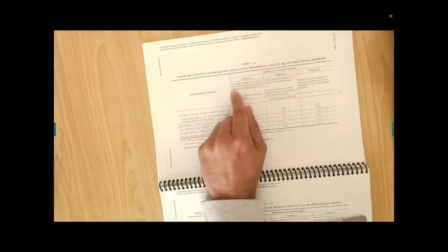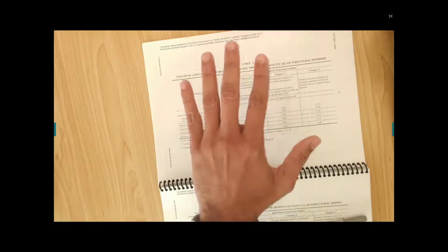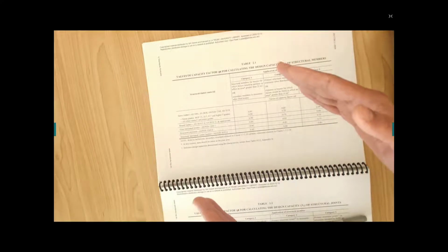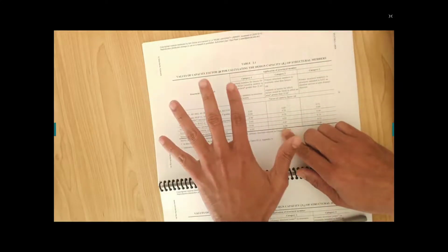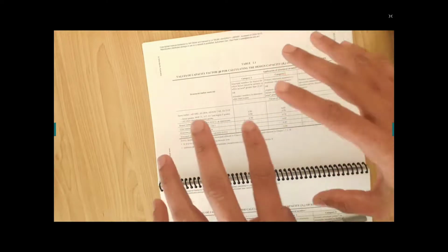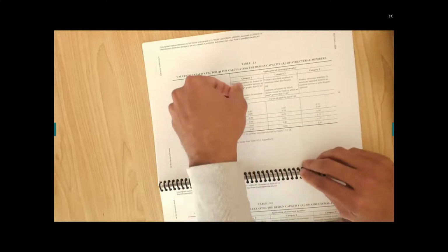Now in those categories, category 1 is a structural member for houses for which failure would be unlikely to affect an area greater than 25 square meters. So if you are designing the timber members in your house which are not primary members, and something happens to that timber beam and it breaks, only a 5 meter by 5 meter bedroom is affected. Not the whole house is affected by that failed beam. If you are designing a beam which will only affect this 5 meter by 5 meter area, your capacity factor is this one.